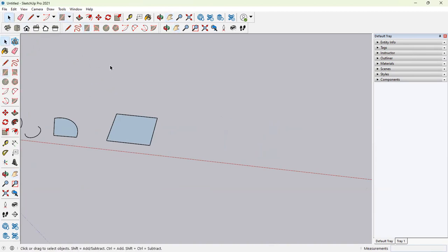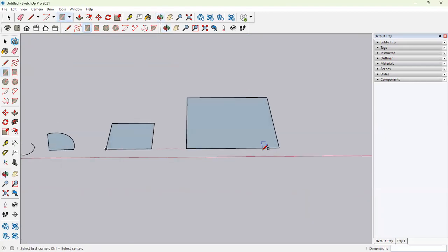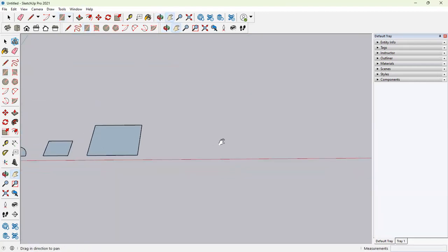This rectangle tool can be also activated by the key R on your keyboard. You stretch and you draw. So you'll have to specify the first point and the second point to draw a rectangle. Now, if you want to have a measured rectangle, you will simply select the R rectangle tool.